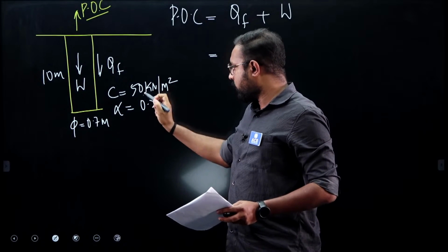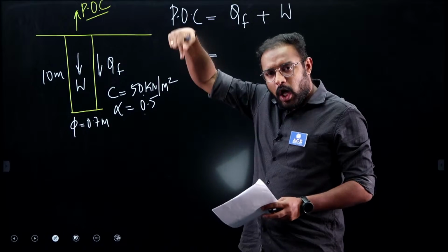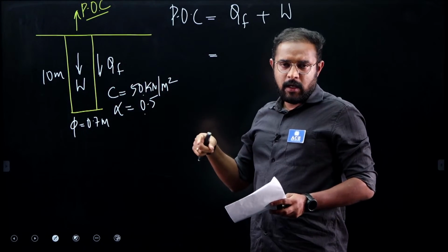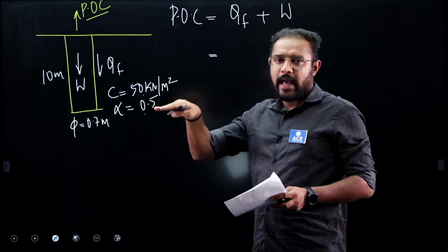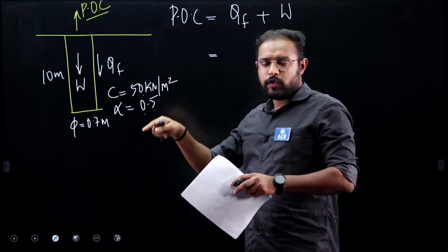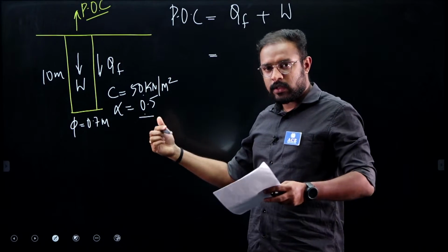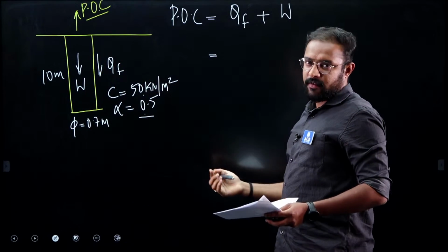The cohesion multiplied by 0.5, just like friction. If the normal force is N and coefficient of friction is mu, what will be the frictional force developed? To calculate the frictional force developed, we can take that factor of force that will be acting against this: coefficient of friction into normal force. Just like that, coefficient into this parameter will give you the force, multiplied with the total surface area will give me the total skin friction developed.